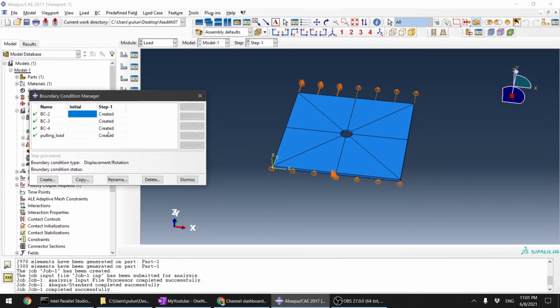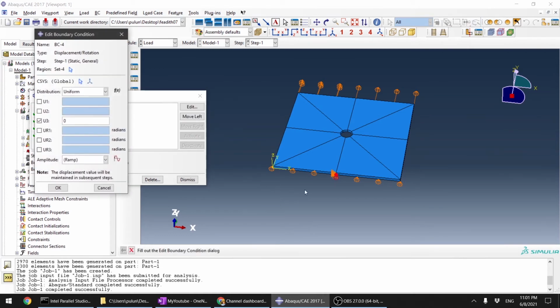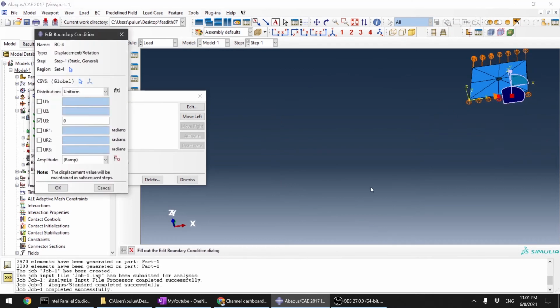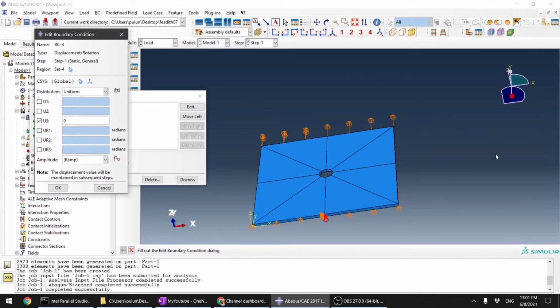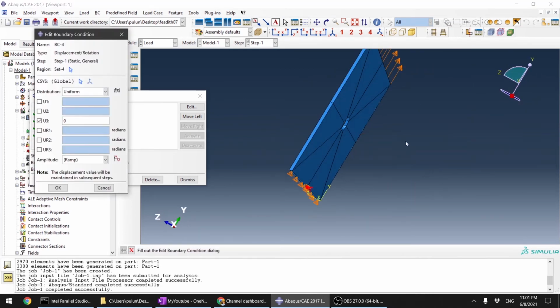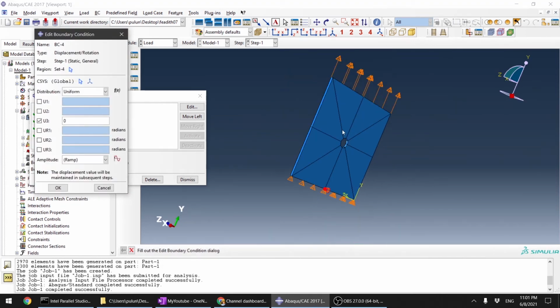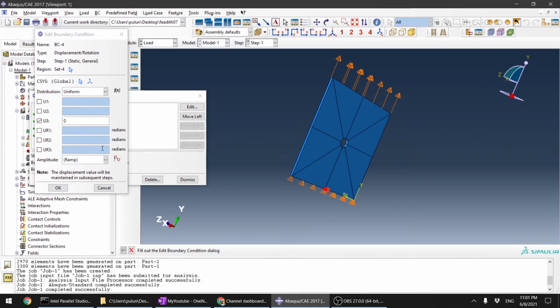previously, for the BC4, we just chose 1 point. This is not enough. If we want to give uniaxial loading, we cannot just push this, because due to numerical error there is out-of-plane movement. So you can click here if you want. You can choose the new set.